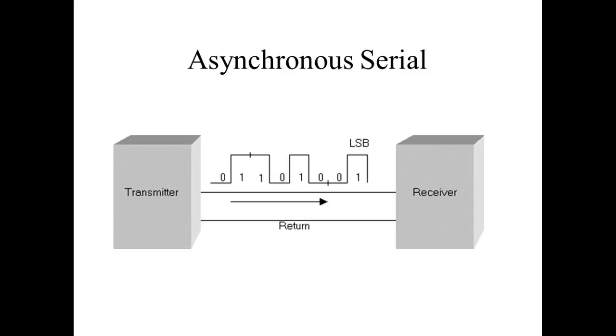Guys, we're sending ones and zeros. How much current are we going to use for those ones and zeros? Almost none. Practically nonexistent, right? Y'all understand that? Which means these guys are extremely susceptible to electromagnetic interference. We call it EMI. So what was happening to us is a magnetic field would pop in here, and it would induce a voltage into that, and it would give us problems.